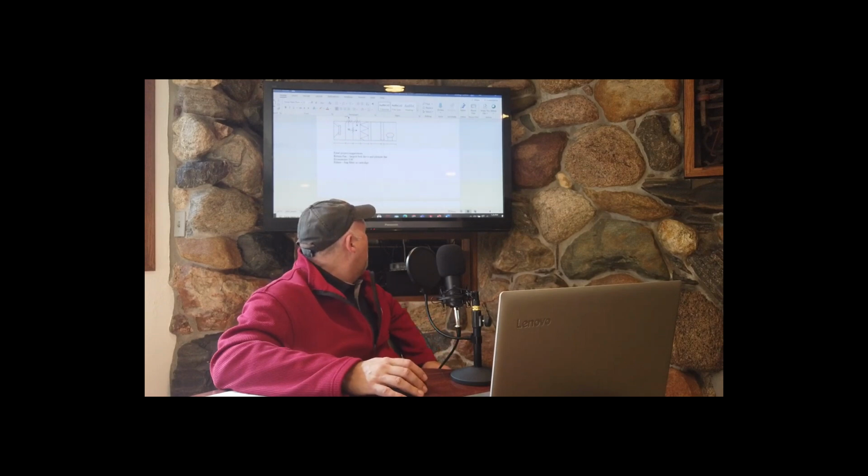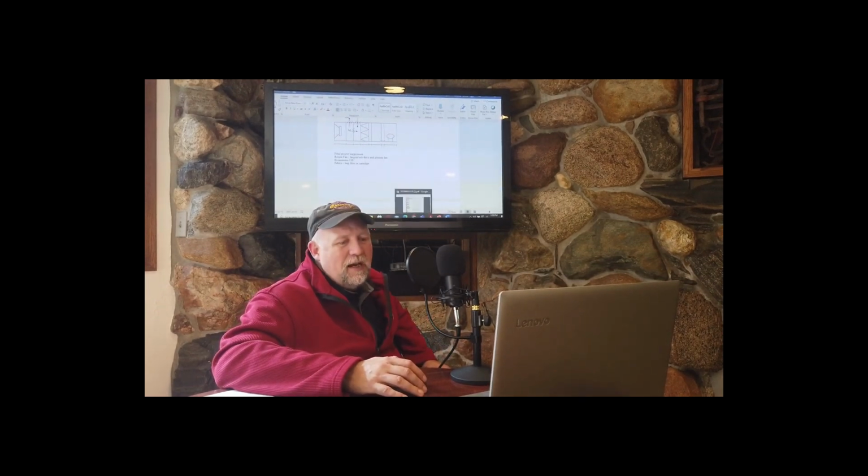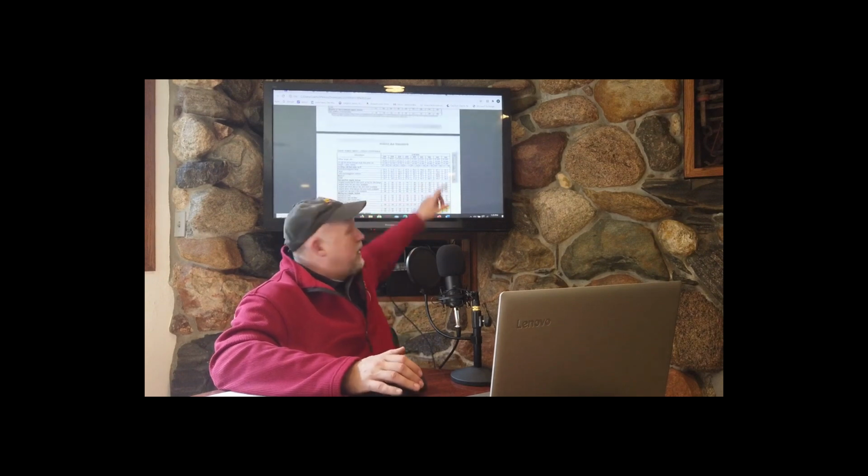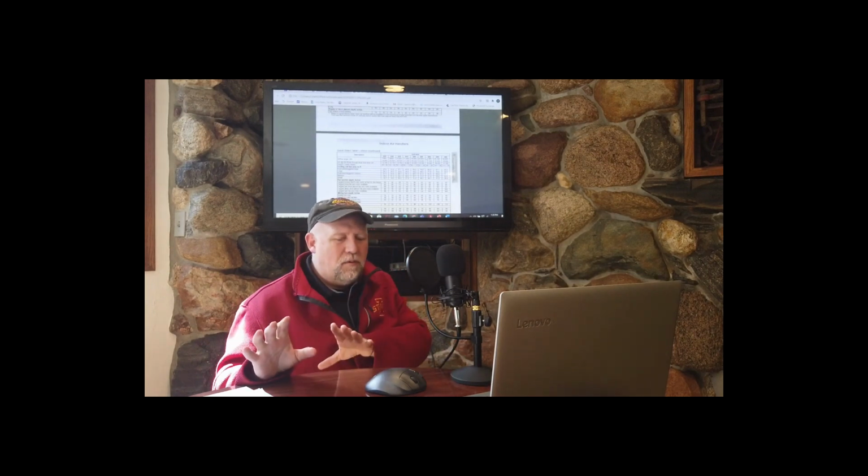Now notice, if you look at this handout, most of you will need an air handler bigger than 40,000 CFM. I did this on purpose. I did an example for a smaller size, knowing you're probably going to have to find the cut section and do this same exercise for a larger air handler. So just remember that part when it comes time for you to pick an air handler and get the size, because for your final project, you have to show me the physical size of your air handler and where you put it in your building.